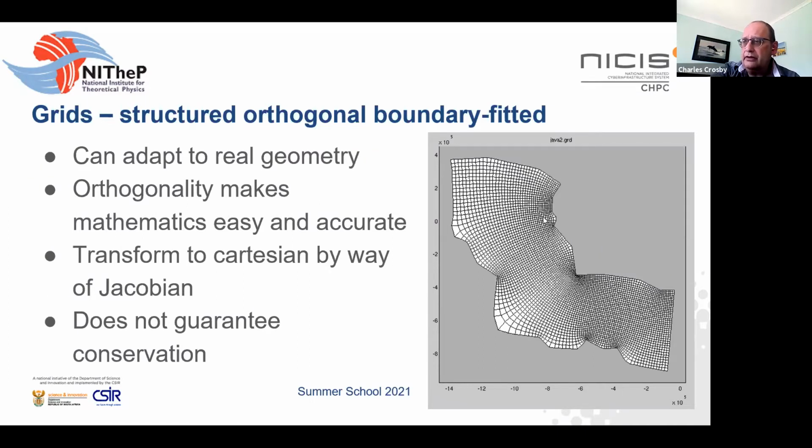So this is quite a useful development, because it means all the simple finite difference methods remain valid, but you can do something that's a lot more realistic. And it's quite astonishing to see how complicated a domain you can actually mesh in 3 dimensions with a single block mesh like this. But there are limitations, and the mesh quality starts suffering at some point. The problem, of course, with using finite difference is that you're actually working with grid points. You're not working with control volumes. So you're not necessarily guaranteed to maintain conservation of your properties.